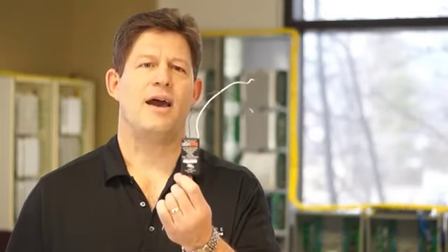I should mention here that some electronic low voltage transformers have been modified specifically to be compatible with forward phase dimmers, such as the Lighttech LET75, as I hold here. The manufacturer of the ELV transformer must state that it is compatible with forward phase dimmers, or an electronic transformer should always be paired with a reverse phase dimmer.